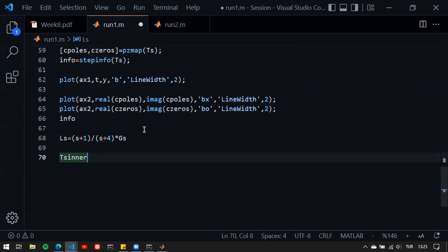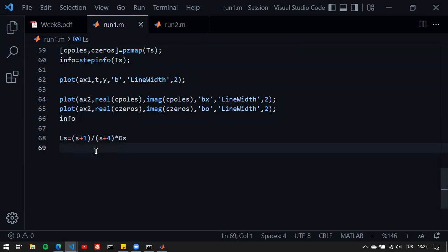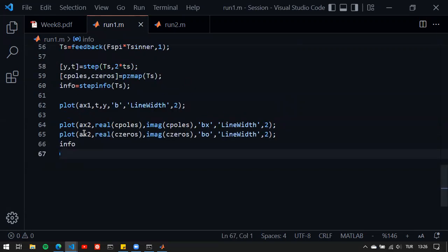So we are not designing the PI controller for the original system. We use a PD controller to manipulate it so that it allows us the best possible dominant pole placement strategy. So therefore, using a PI-PD controller is really important. It is basically a PID controller, but it has an additional freedom that allows us to place the zeros. Most of the time, we have to stick with the PID controller zeros. If we are using tabulation, we still try to push them out of the dominant region. But in this case, we are able to place the 0 as we want.